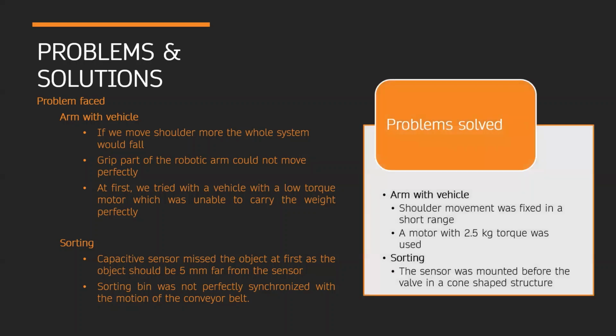For solving those problems, we have changed some things. For a short range, we fixed the shoulder movement. Then we have used a higher torque motor. Also, the sensor was mounted in a cone-shaped structure for solving the sorting problem.